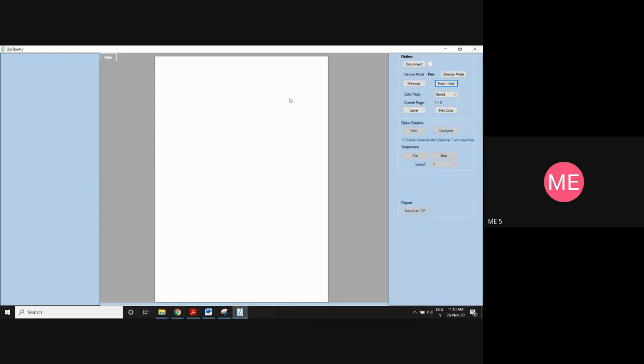Now, as usual, to solve the problem, assuming high speed turbine. We don't know whether it is high speed or low speed, we are just assuming it at the beginning of the problem. The velocity triangle is as follows. Alpha 1, beta 1 dash, this is beta 1. VR1, VF1, V1. The distance from alpha to beta is considered as U1, and alpha to VF is always considered as VU1 in all the chapters.